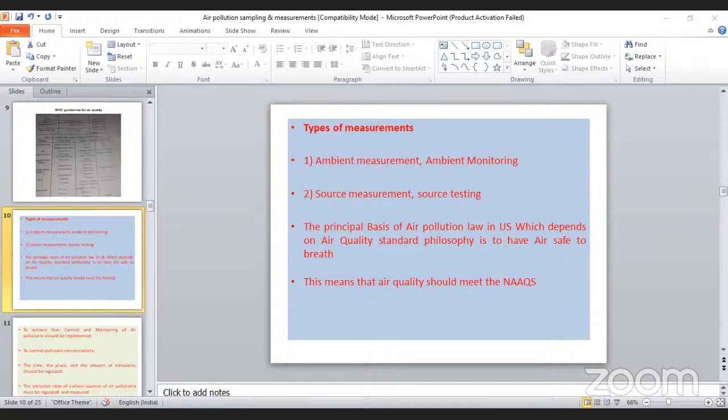It is very wonderful. Even if you do any reaction, and any volatile chemicals are coming out, if you want to make qualitative and quantitative study, both you can do by following this impinger bottle concept. We can come to know to some extent, and sometimes it is possible to give an accurate answer also. It is an adaptable technology to quantify any gaseous pollutant or gaseous mixture released from any chemical process, not only for pollutant analysis. Okay. And monitoring of air pollutants we'll discuss now.